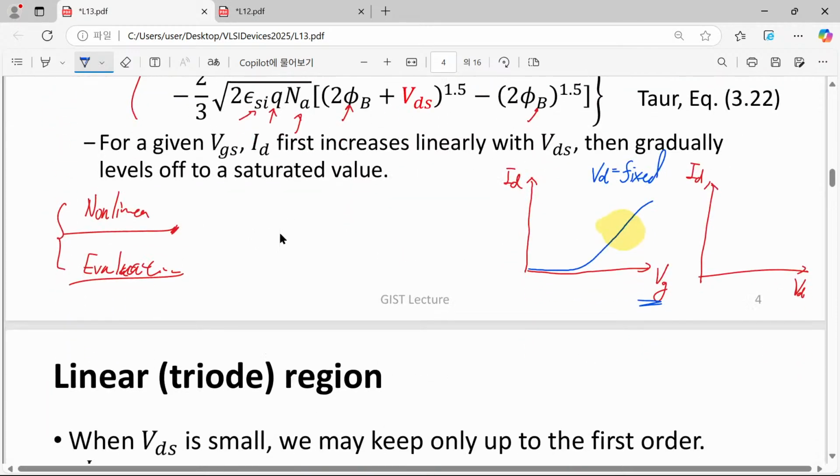And another one is we will have this kind of output characteristics. Yes, this is the output characteristics of our transistor. When we have a sufficiently low gate bias, there will be no current conduction, so this is out of our interest currently. And where are we now?